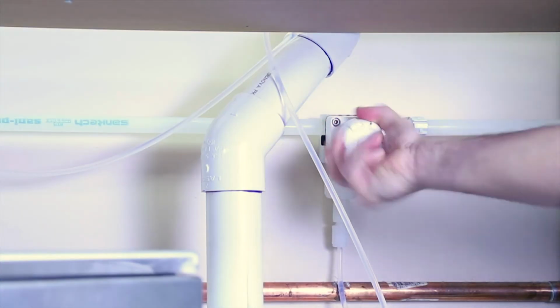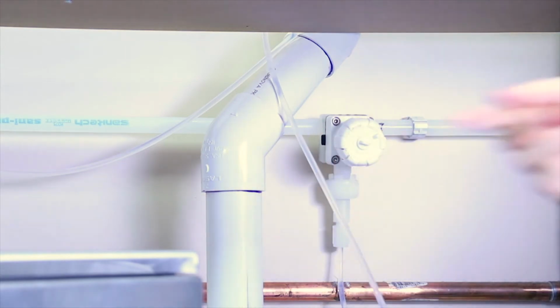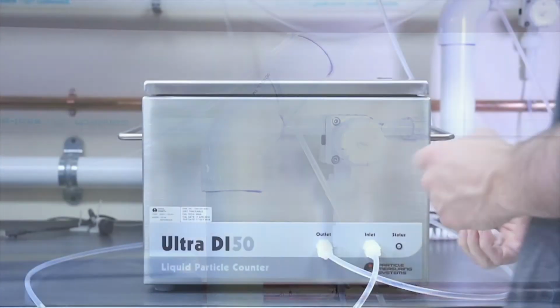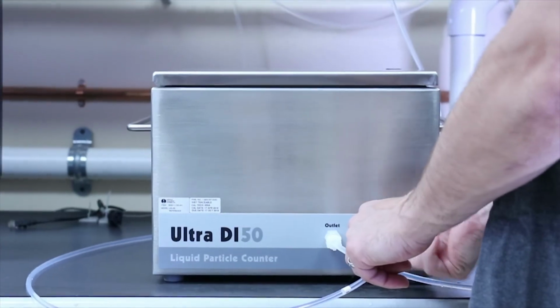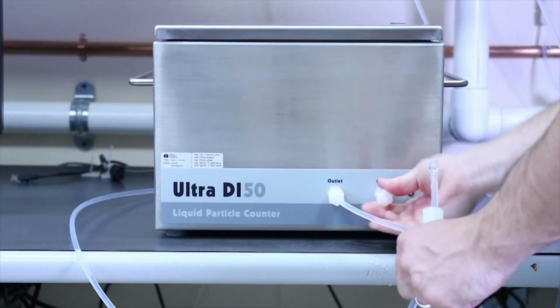Start by turning off the flow of the UDI 50. Disconnect the inlet and outlet lines and install them to the standard configuration with the inlet line going to the inlet port on the instrument and the outlet line to the outlet port.